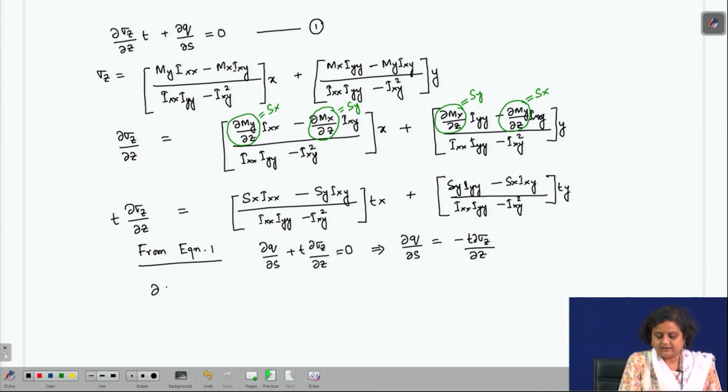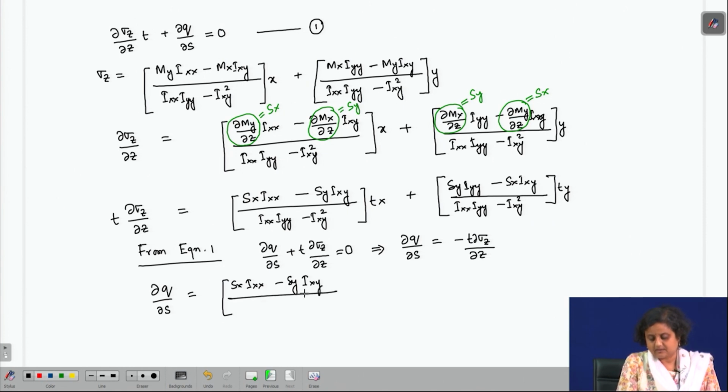So, therefore, del q by del s can be written as Sx Ixx minus Sy Ixy by Ixx